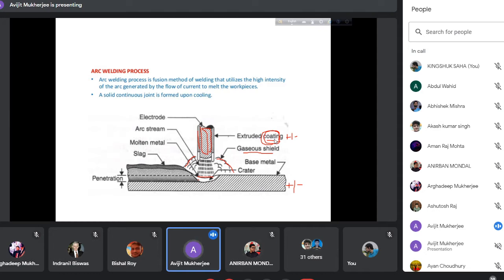Now, I think you have gone through the forging shop. In this case, when the job is heated, sometimes due to overheating, what do you do? You sprinkle water, or immediately dip it inside the water tank. But what is the concept of this? Dipping from a very high temperature to a very low temperature suddenly is the concept of quenching, rapid cooling.